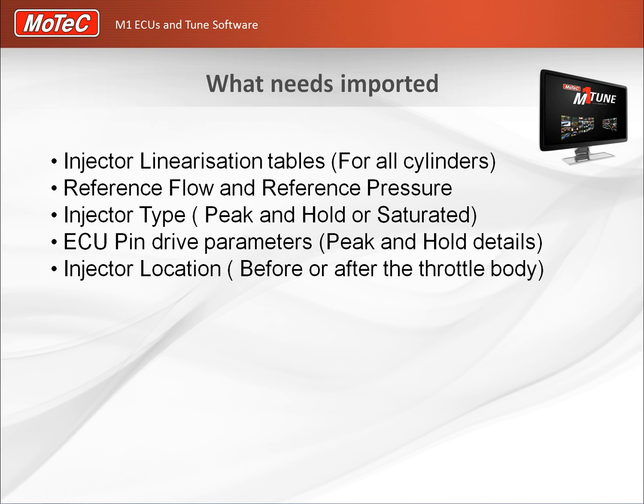There's quite a bit of information that the ECU needs to know about. It needs the injector linearization tables to be entered. This is like, in M800 terms, the battery compensation tables. There's a slide coming up that shows you a little bit more about that. Then the reference flow and reference pressure. Briefly, this is the maximum flow of the injector and the pressure at which it was flowed.